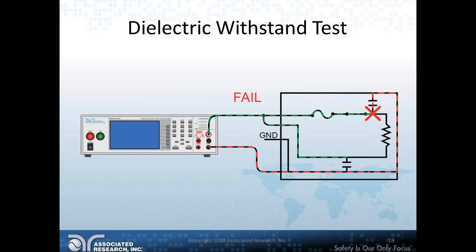The dielectric breakdown, on the other hand, can be defined as the complete failure of an insulation to effectively prevent the flow of current. Sometimes it's evidenced by arcing. If the voltage is raised gradually during a high-power test, breakdown will begin at a voltage level where the current flow is not directly proportional to voltage.